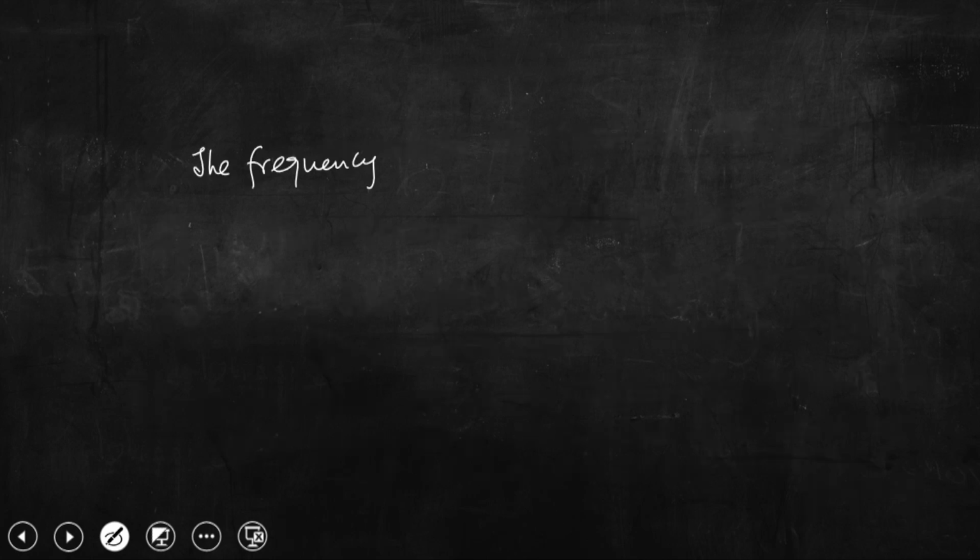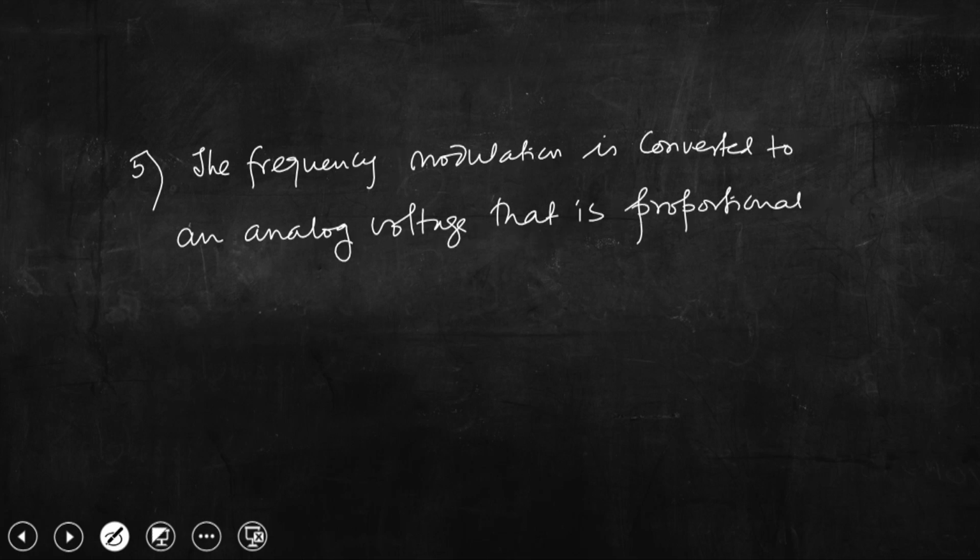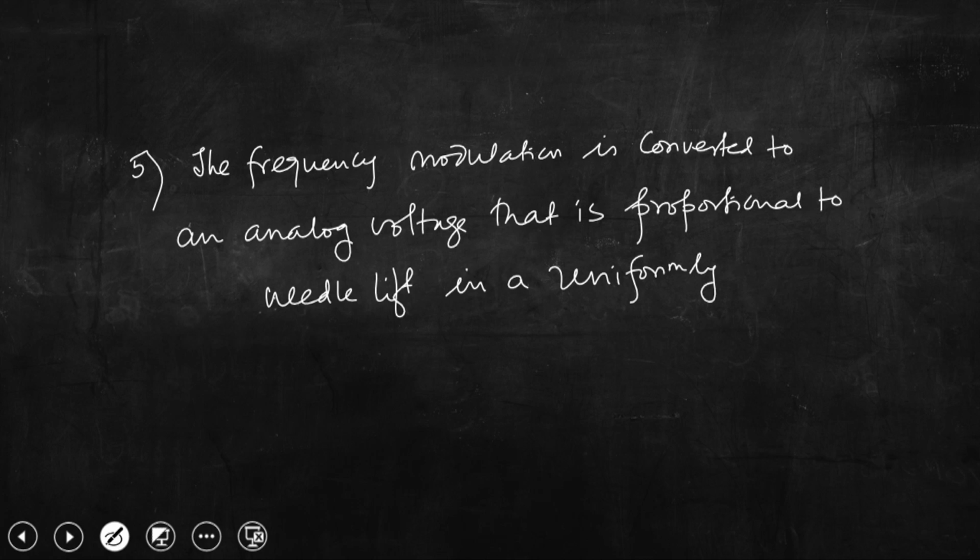If we go back to the previous slide, this is number 5, the frequency modulation is converted to an analog voltage that is proportional to needle lift in a uniformly wound coil.